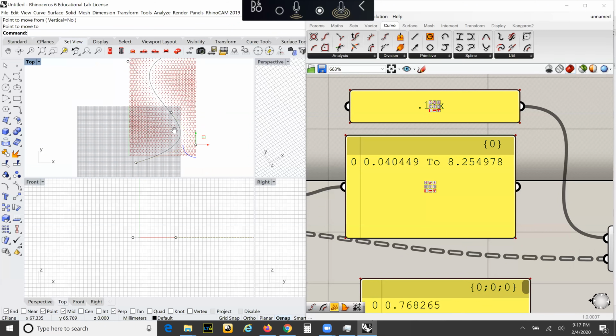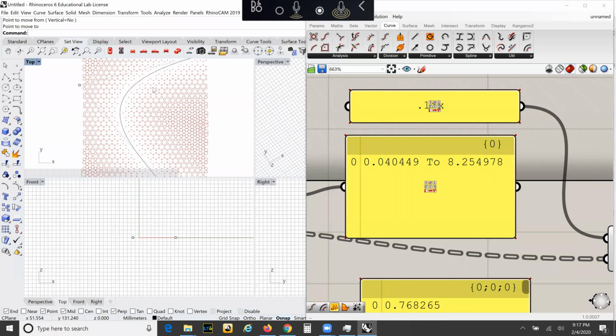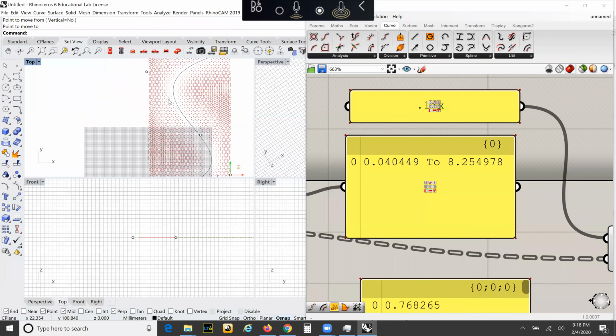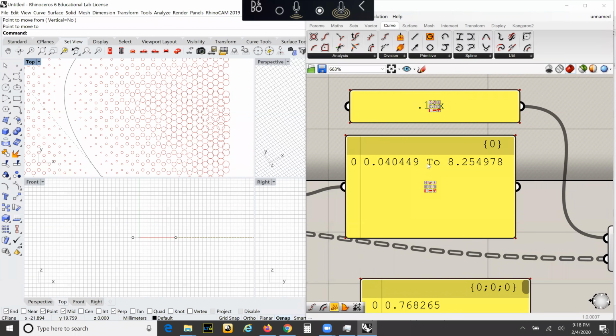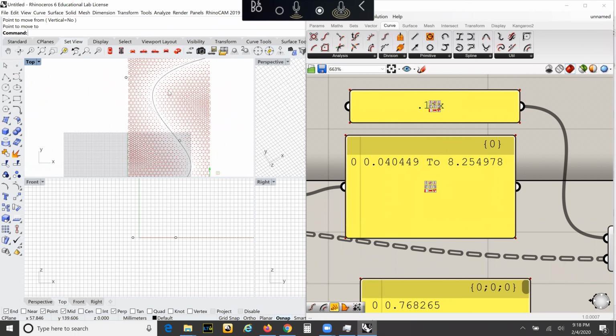So this becomes a lot easier for someone to CNC or laser cut. Now they don't have to get rid of all these little holes. Another application that we've used these on have been stair rails, like for code, stair rail or guardrails. You can't have a circle that's greater than 4 inches. So we want this great pattern, but we don't want anything that's greater than 4 inches.